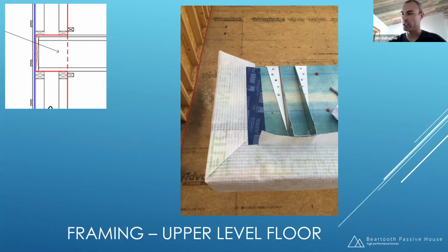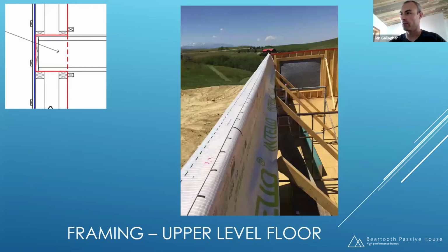Okay, so just think through if you have projects where you have an exterior wall that is structural and you've got things sitting on it, or kind of sitting on it, but also that break it up a little bit, like we had a beam pocket. Those aren't easy transitions to get out and around, so think through it before you ever do it, and maybe make a mock-up and figure out how you might get your air barrier out and around it, because that could be pretty tricky for you.